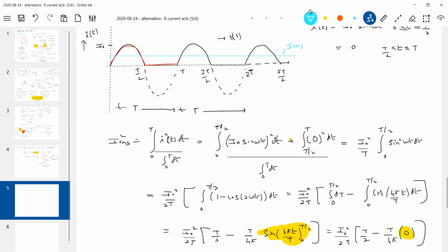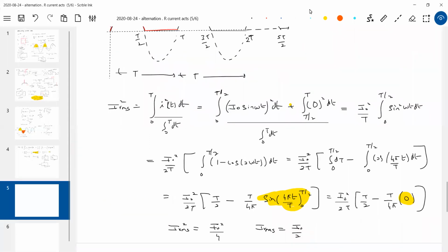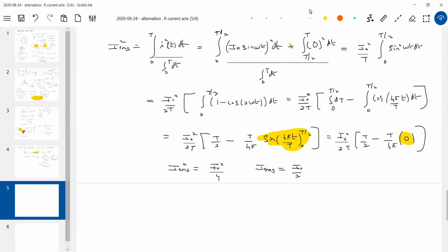It's hypothetical. It means if a current varying sinusoidally like a half sine wave flows for an interval of time, some amount of heat is generated in that interval. If you send a current equal to I naught by 2, the same heat will be generated. So this is the equivalent, the interpretation. So got the idea, no? So this is for the half sine wave.